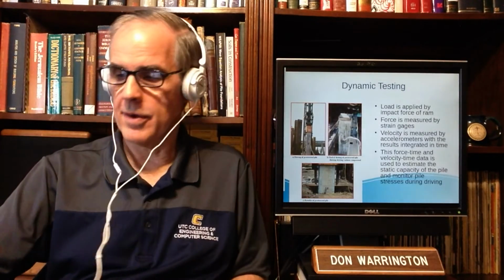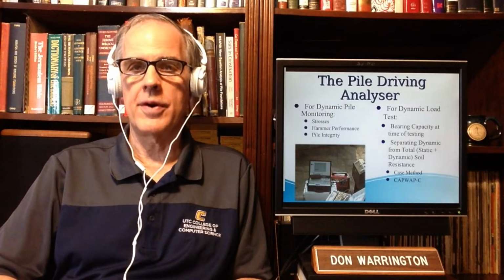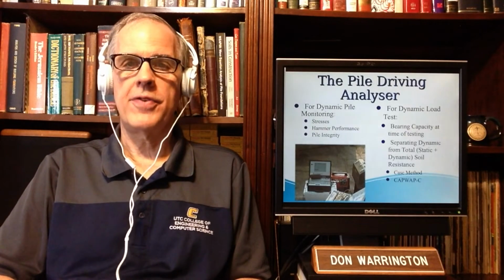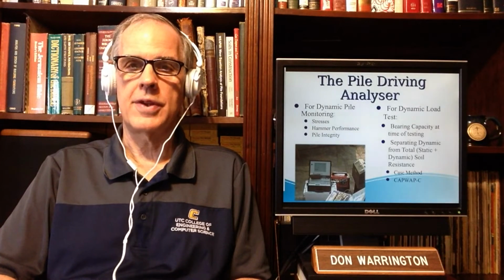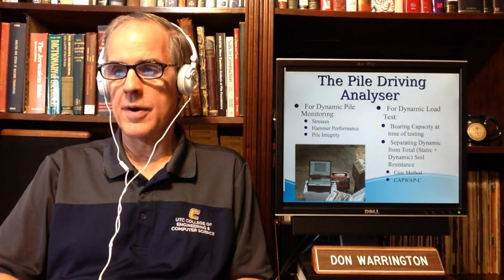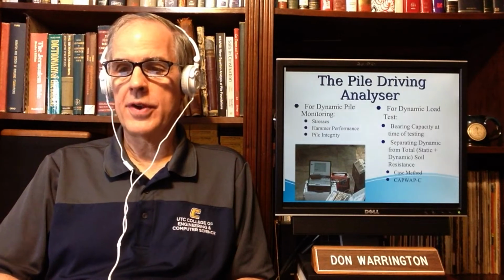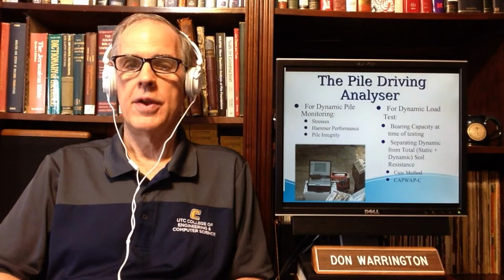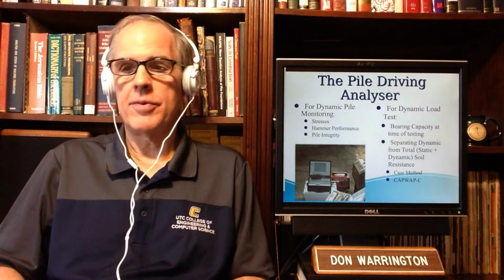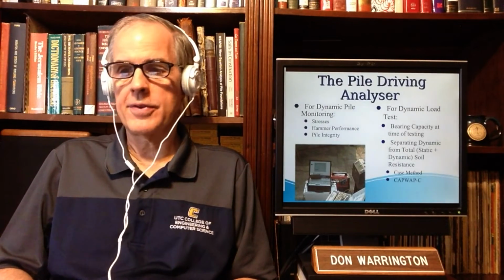Well, I'm getting ahead of myself. Pile driving analyzer. Once you get all this data going into a pile driving analyzer, now of course they've got ways where you can gather it in the field and transmit it to the office, with somebody sitting in the office watching all this and gathering the data. And you can derive stresses and the hammer performance. You can also do pile integrity, which I think you saw in the pile wave demonstration. For a dynamic load test, you get the bearing capacity at the time of the testing.